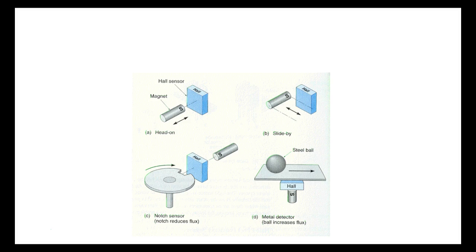So all we got to do is just attach a magnet to whatever we want to sense the position of. If I've got magnetic devices, then we don't need that. But it's a non-contact sensor. That's a big advantage, non-contact. The problem, anytime we bring two things in contact with each other, we create friction and they wear out. So that operator on that limit switch is going to have to be replaced sooner or later because it makes physical contact with something, right? You understand? Now, sometimes they'll put rollers on them and try to limit that, but they all go bad sooner or later. So a limit switch will go bad, what? Sooner or later.